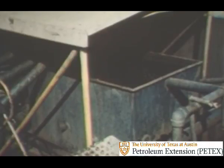Here, a roof over the mud pits keeps rain out of the mud. This is necessary in areas where heavy rains may add so much water to the mud that the mud would thicken and require additional emulsifiers and chemicals to maintain good mud properties.